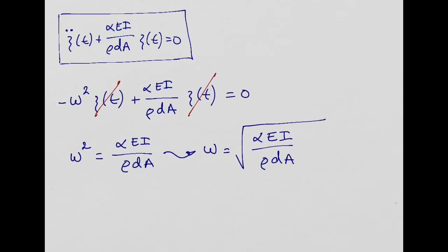which I think you are familiar with from last year with Chris Myers, he did vibrations, right? Spring and a mass, right? You remember you calculated the natural frequency of a spring and mass system, right? You obtained for that spring and mass the natural frequency as being the square root of the stiffness of the spring over the mass. Remember this from year 2 vibrations?